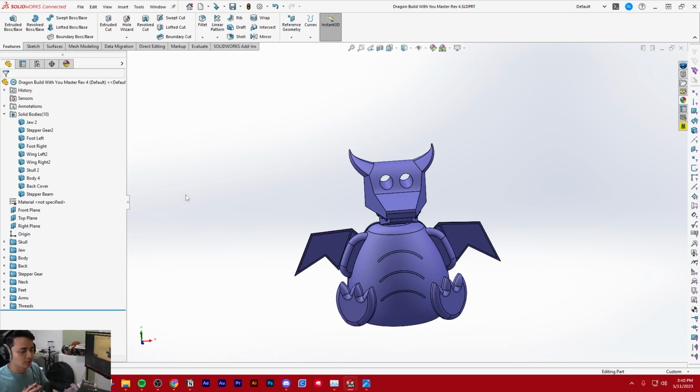The next thing that we're going to work on is, so we have a master file with multiple bodies of all the parts we designed, right? So now what I want to do with that one, and our master is in one part component file, I want to take all of those bodies and then put them in an assembly file and have each separate body be its own part.